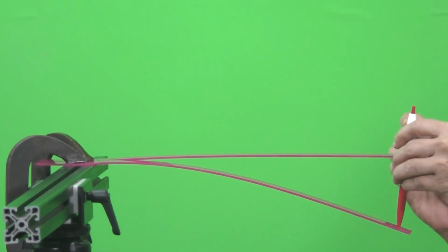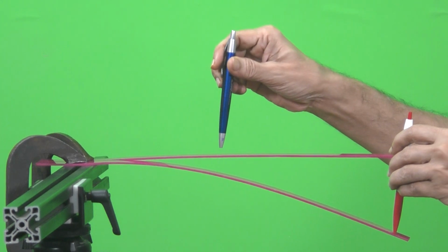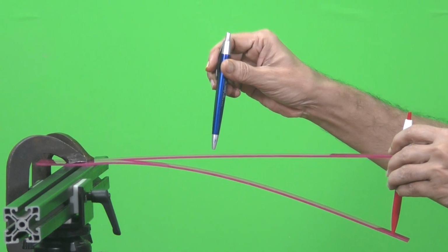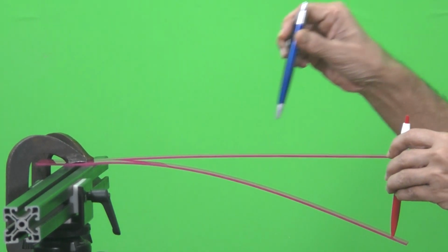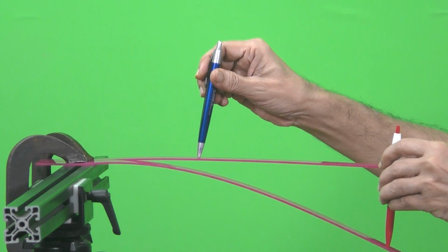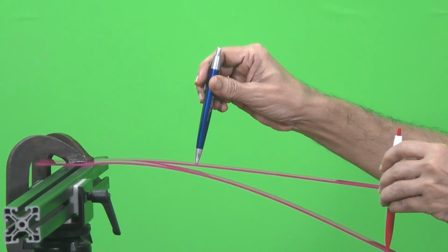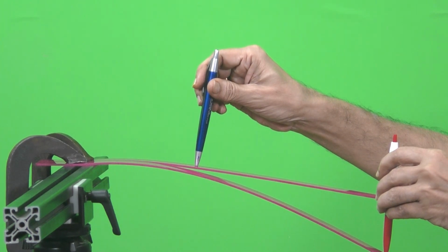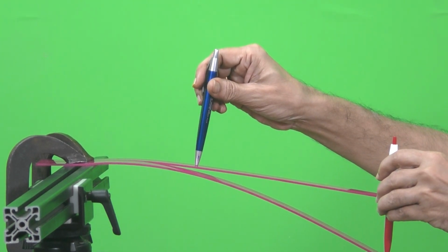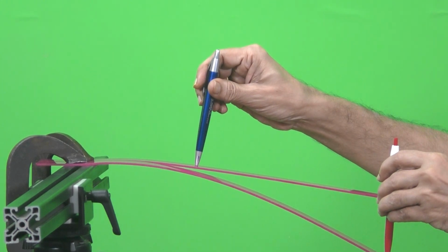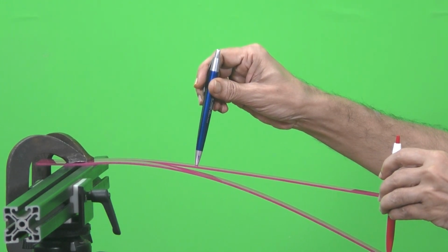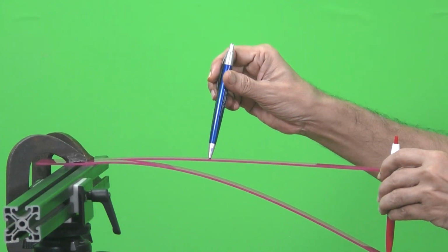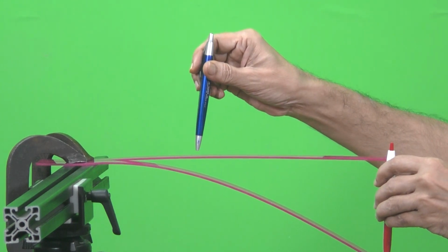Now, I take this beam and I apply load somewhere in between. Technically, I have no load on this section. When I apply the load, I want people to recognize what is the deflection up to the load application point from the fixed end and what happens after the load application point to the free end in the second beam. So, this section remains straight but rotated. Okay, that you have to recognize.